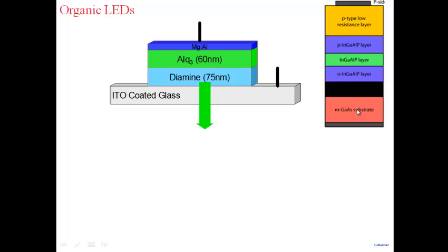One can have more organic layers, just like you have a series of semiconductor layers; here there are two. Both these layers are amorphous. They are no longer crystalline. They're amorphous semiconductors; one belongs to the amine family, and this is Alq3 here. Amorphous means there's no order, right? No long range order.